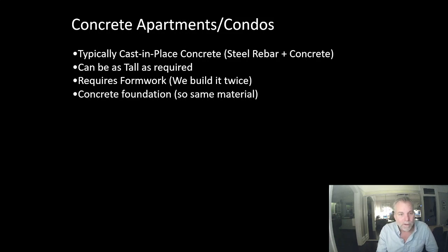So, concrete apartments and condos. Typically, multi-residential is cast in place concrete. The form is erected, rebar is placed on top of the form, concrete is placed on top of that. The concrete cures, and as soon as it's self-supporting, the form is demolished underneath.